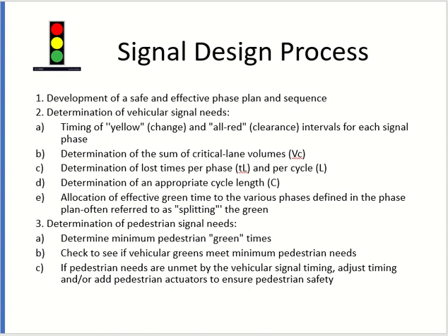The pedestrian needs 10 seconds. Are you giving at least 10 seconds for the vehicle green? If it is, fine. If not, and it is less, increase the vehicle green. Okay? And pedestrians normally cross parallel. So if the vehicles are going towards east, they have the green towards east, the pedestrian will go parallel to them. Okay? Clear?